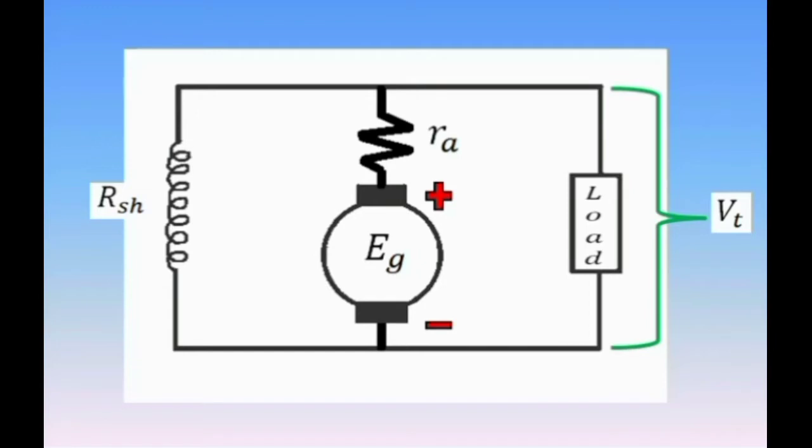We will be using Kirchhoff's current law and Kirchhoff's voltage law, and again combined with power formula and Ohm's law. We know the generator delivers electric power, and that power comes from the armature. So there is a current coming from the armature indicated as IA, or the armature current. Its direction will follow the conventional current flow, which is from positive to negative. At this part of the circuit, only the armature current flows.